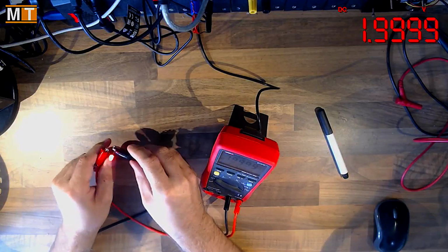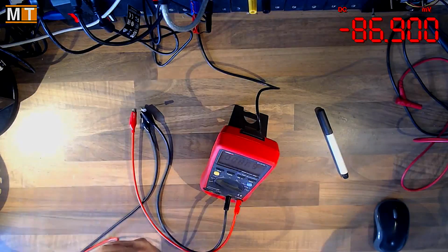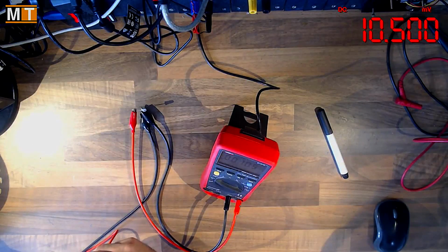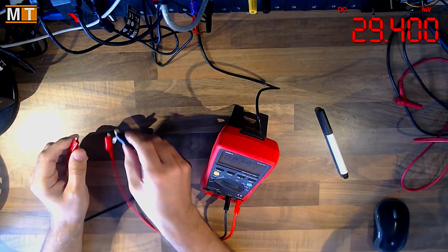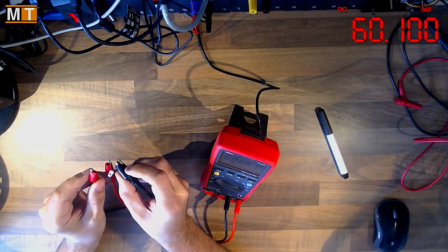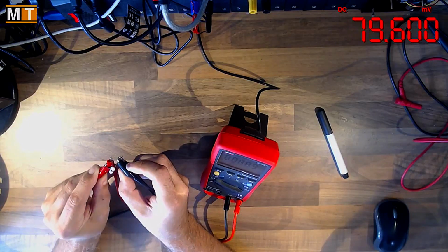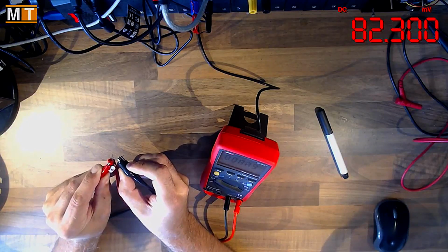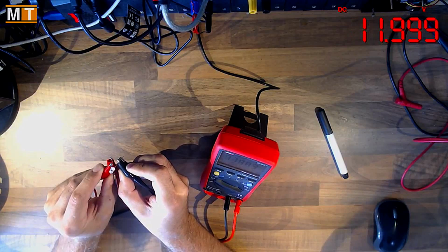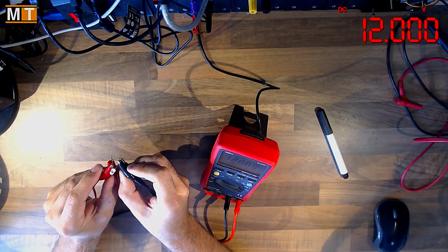Okay, I'm now going to do the same. This time I'm going to pump the voltage right up to 12 volts, but still limited to 20 milliamps. What's going to happen when I connect this? Is the LED going to blow, or is it just going to light up like before? Here we go. Bang! That blew.